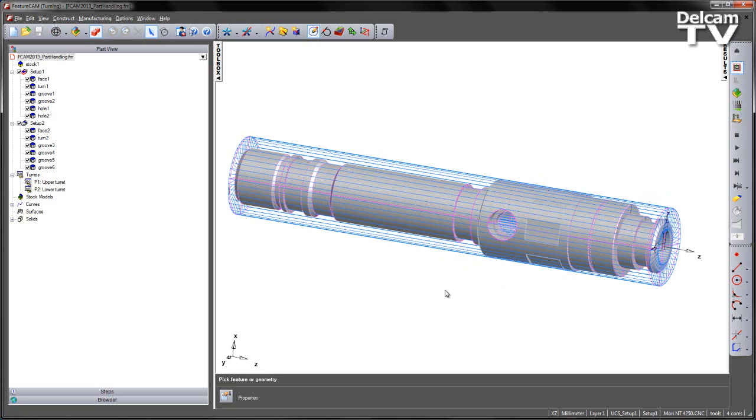In earlier versions of FeatureCAM we would have had two options. The first option would have been to transfer the part using the individual transfer features, and as we moved on through the process we then brought in the transfer UDF. We now have part handling as a feature which combines multiple operations together.